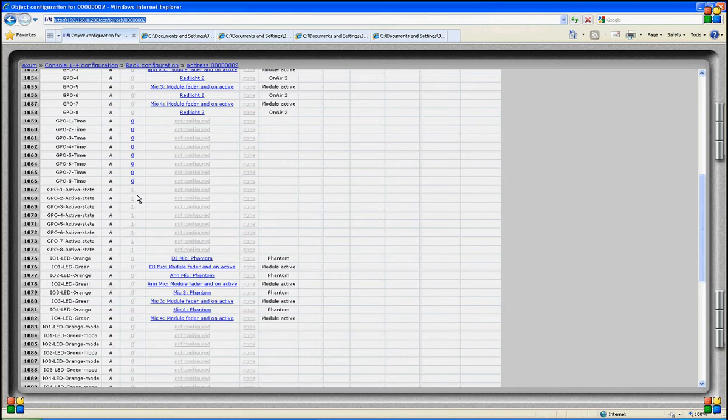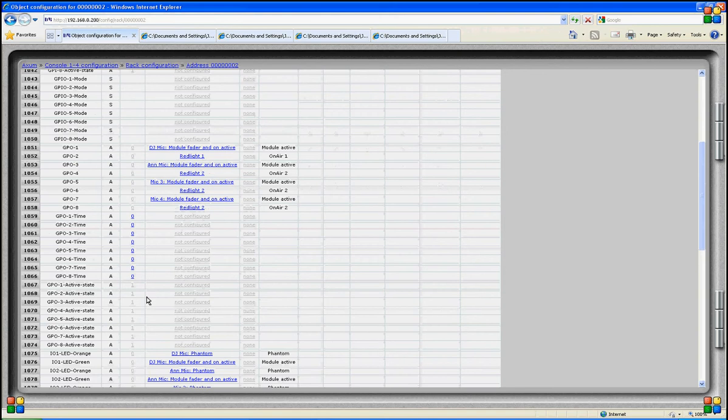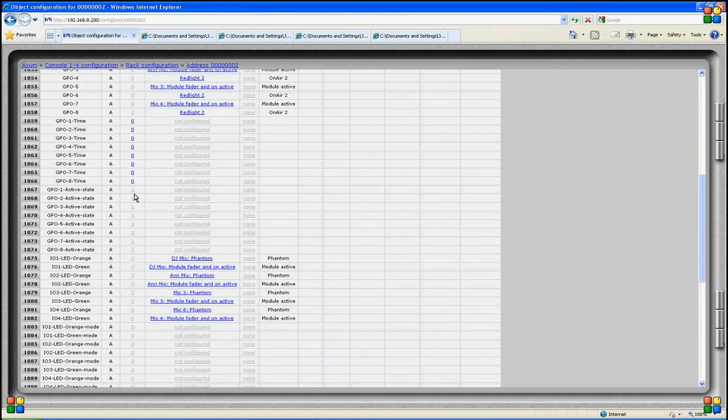Active state 1 means that a positive signal comes out of the GPO when activated. Active state 0 means that no signal or no action is present. Many devices are different, and some need a reverse GPO signal. Some respond to a 1, 5 volt, and others to 0.